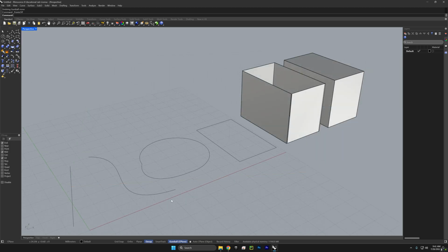Surfaces can also have their control points turned on. Let's give a quick example of that. As a first step, let's take this control point curve that we created over here and run the ExtrudeCrv command. Extrude curve, and bring it up to about there.